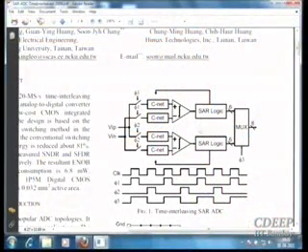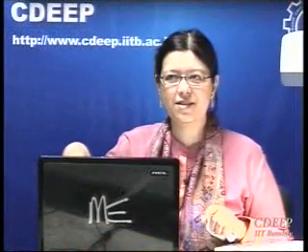But actually, you can have a sampling frequency of 2 Fs. So you give the first sample to the upper one, the second sample to the lower one, the third sample to the upper one again. The first ADC will receive odd samples, the second ADC will receive even samples.